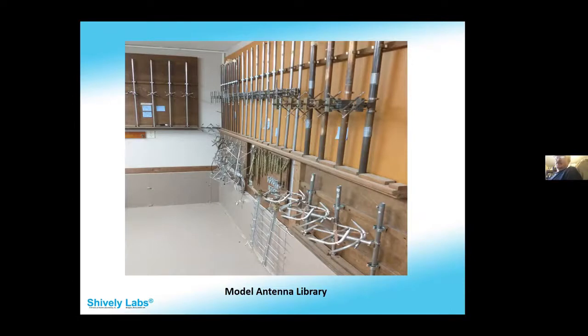And we actually have something called a field probe that we use. It's like an I-beam with a motorized carriage on it, and it takes a probe up and down, and we can actually sample the vertical and the horizontal field. You want to try to get it within half a dB or something like that, if you can. I know sometimes it's a compromise, especially at this frequency. But there's an art to it. We've got folks whose whole job is antenna measurements. So it's kind of fascinating.